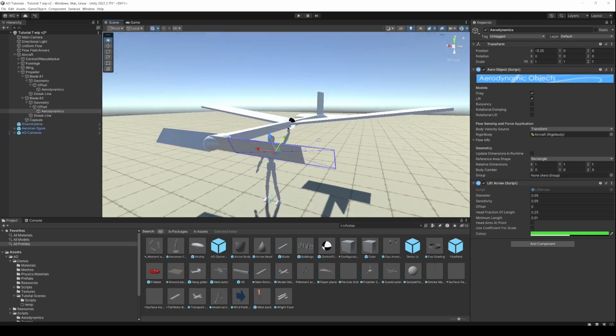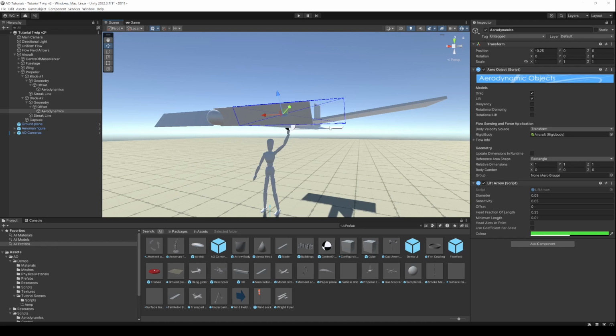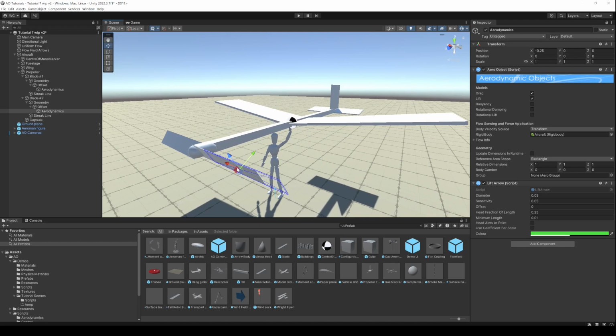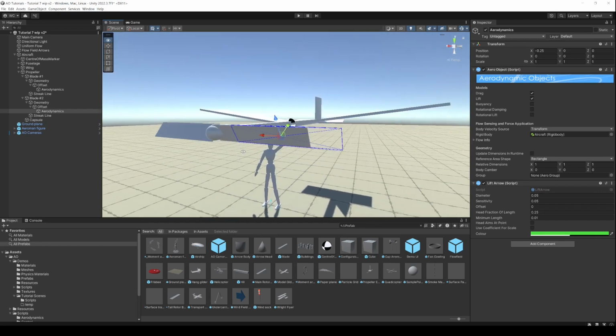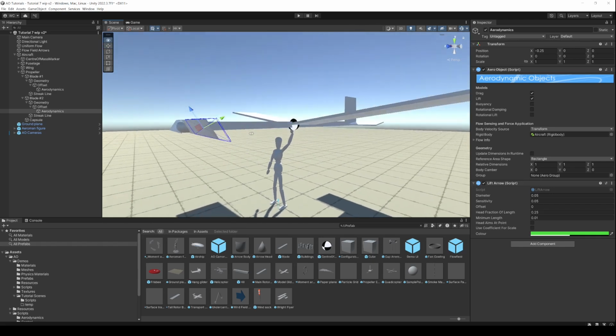So we're not doing panel methods or CFD, but we're using that geometry to make a reasonable approximation of what that blade has done. And if you compare this model to actual data you get from doing thrust experiments on propellers, it's actually pretty good. Even just using one control point like this on a blade, you can get answers that are within 10-15% of what you get if you did a real experiment.